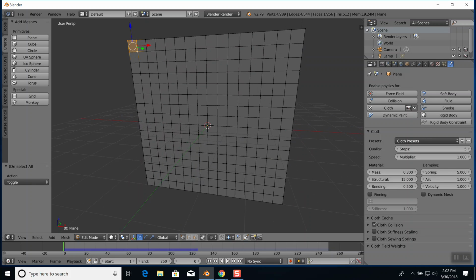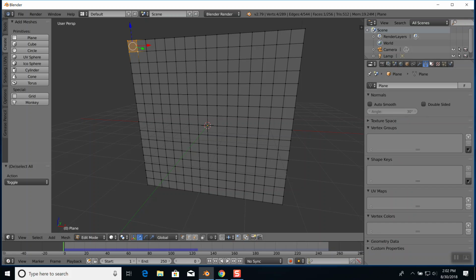So I'm just choosing those first four. Now over here there's what looks like an upside down triangle with 3 white dots. See that right there? We're going to create something called a vertex group. A vertex group basically says that we're taking these 4 vertices and assigning them to a group, so we can do something with it.